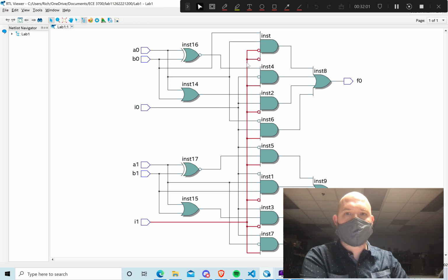And then same thing here, I could look and say this is not I1, but for some reason we're getting two inputs of not I1 into this, which seems odd. Not sure why we'd have that. So maybe that's something to look at. Maybe that's something that's not quite right. It shouldn't necessarily cause a problem, because not I1 and not I1 is still not I1, but it is strange, so that's worth looking into.